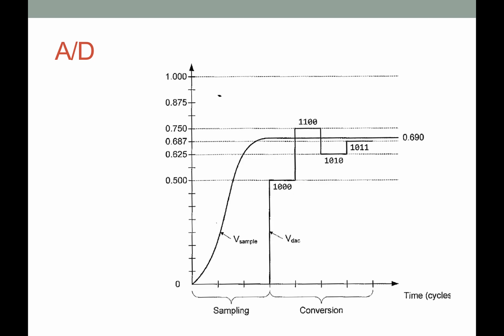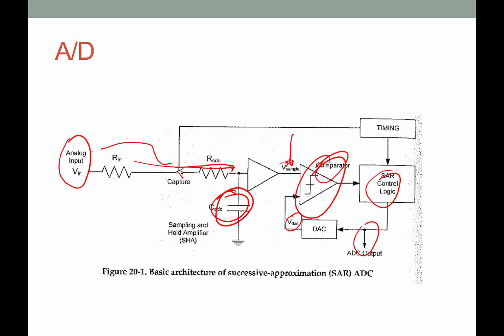So here's what we have going on in this example. You can see what's happening right here: this is where the voltage is being sampled, and we have to take some sort of conversion time, and it has to settle. We don't want to sample until that capacitance is charged to that level, or we get the wrong value. Once we can sample, the first thing it does is change the most significant bit as it goes into the comparator.